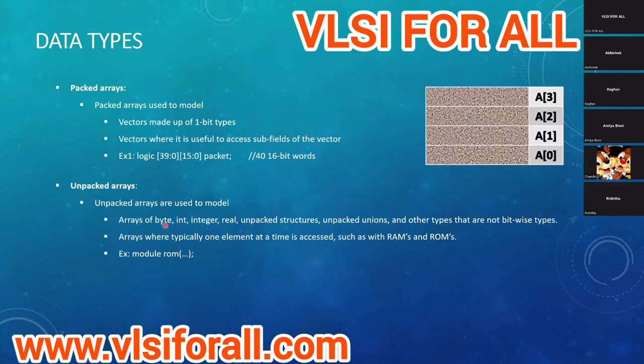For example, in RAM and ROM, you will always access one memory location at a time. So there you will use an unpacked array, but every memory location will have maybe 8 bits or 16 bits. So there you'll use an unpacked array to represent one memory location of 16 bits. For example, this is an unpacked array, byte M 0 down to 4095. It represents a memory of 4096 bytes, which means 4 kilobytes.